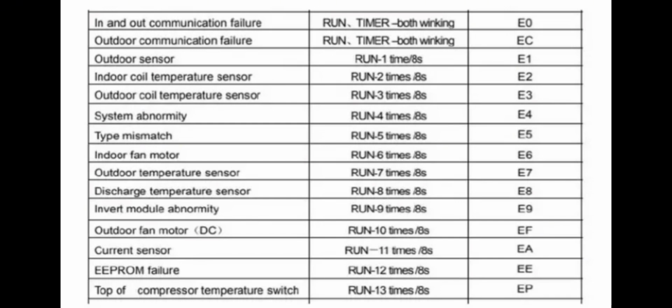Check if the refrigerant is at the correct pressures. You need a technician to do that, or if you can check if the pressures are okay in your system, and check if the temperature sensor on the outdoor condenser unit is not loose or broken. Sometimes it's possible, especially if you have trees or something around it, or you might need to replace the indoor main PCB.